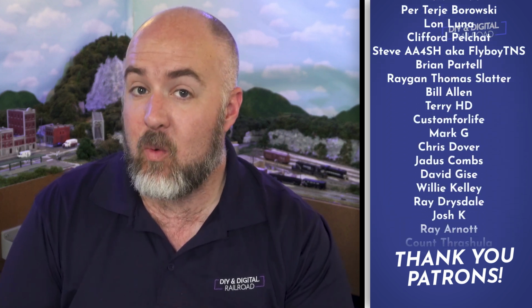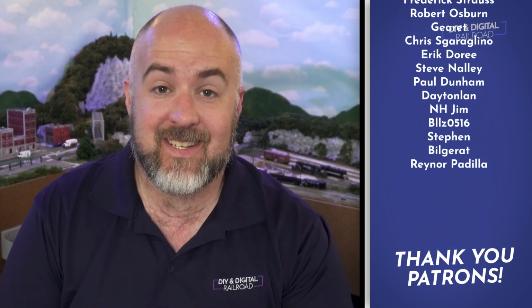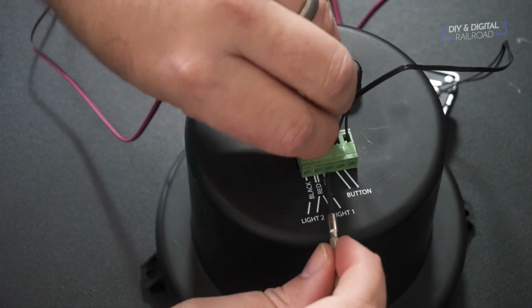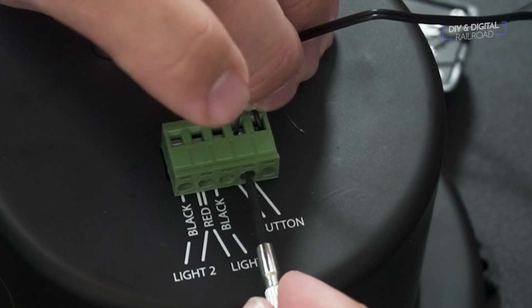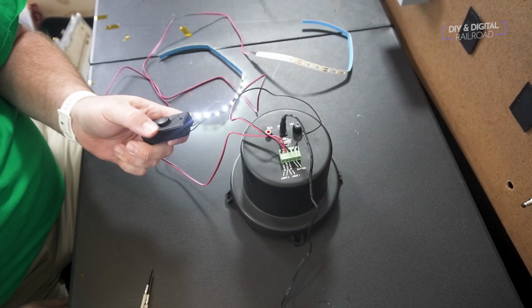Now, one thing that I wanted to know was, can an Arduino control this? The answer is yes, and I'm going to show you guys in a bit. But let's check out the lightning storm first. This thing is pretty simple to set up. All you have to do is connect the LED strips to the marked connectors, then connect the button with the included jumper to the marked connectors for the button. Then plug it in and you're ready to start a thunderstorm.